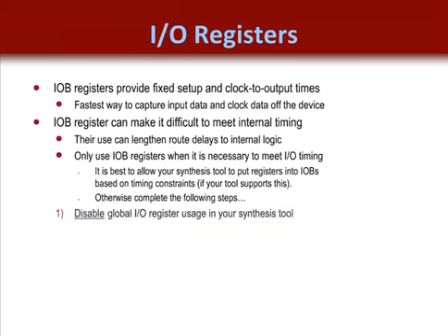Step 1. Disable global I/O register usage in your synthesis tool. This will prevent the synthesis tool from mapping these registers to the IOBs every time. This option is usually on by default.